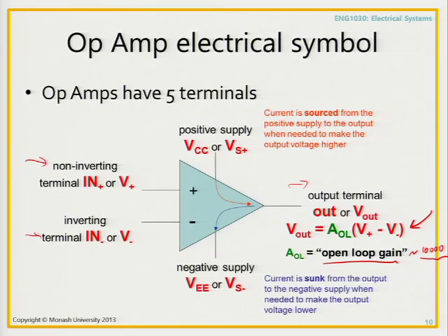Physically that doesn't quite make sense, and the reason is that, like any electronic component, this op amp requires power. That's what these two terminals are. These two terminals are called the supply terminals, and these are signified via these abbreviations, VCC or VS plus, and VEE or VS minus. The top one is usually the positive supply, the bottom one is usually the negative supply. So what do these two things do? Well, we connect up, as the name suggests, a supply voltage, and this might be, say, 5 volts up here, and this might be negative 5 volts.